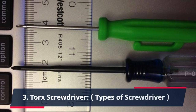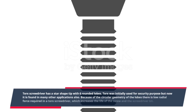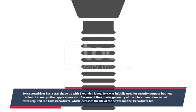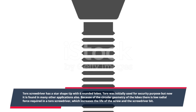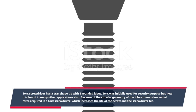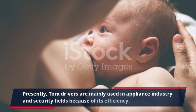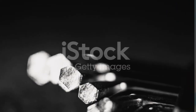3. Torx screwdriver. Types of screwdriver. A Torx screwdriver has a star-shaped tip with 6 rounded lobes. Torx was initially used for security purposes, but now it is found in many other applications also. Because of the circular geometry of the lobes, low radial force is required in a Torx screwdriver, which increases the life of the screw and the screwdriver bit. Presently, Torx drivers are mainly used in the appliance industry and security fields because of their efficiency.